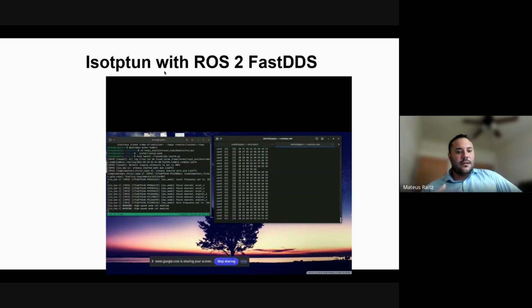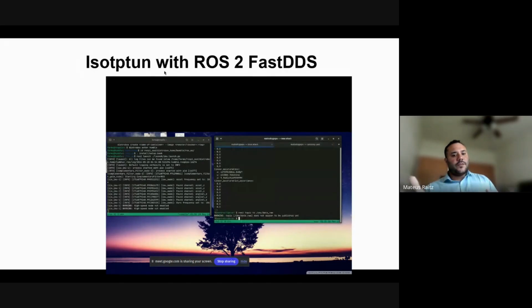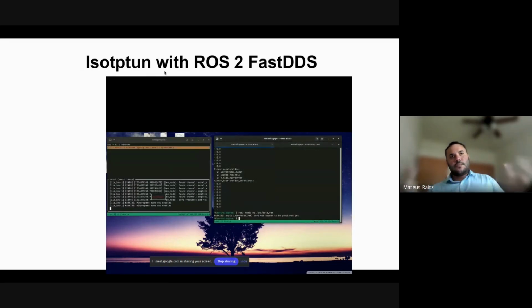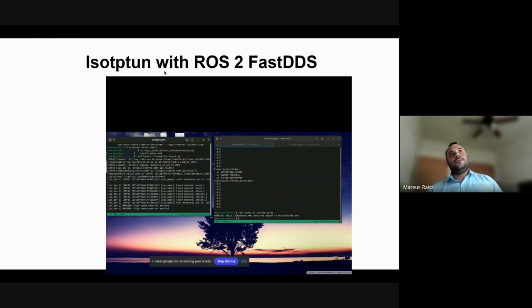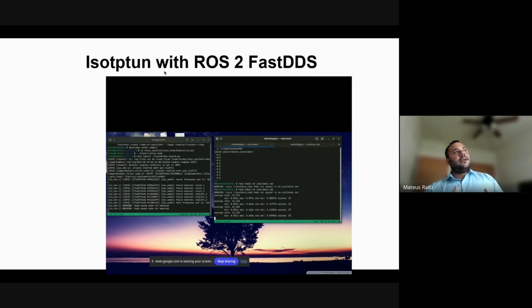But it's just a proof of concept to open up the conversation to develop more uses of micro-ROS or ROS2 with CAN FD as a transport layer, like having DDS and ROS2 support CAN natively.